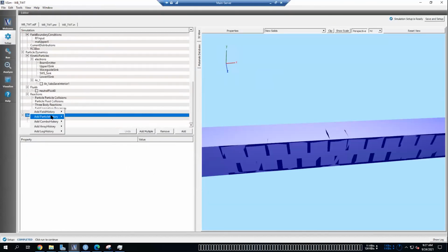can define particle histories, and you can look at your emission current, and then you can look at your absorbed current. If you define absorbed current both at the upper X, which is your exit, and the lower X, which is your input port, then the difference in between will give you the ratio between transmitted and reflected, or if you compare the transmitted to emitted, you can see that too. But that diagnostic can be easily added.